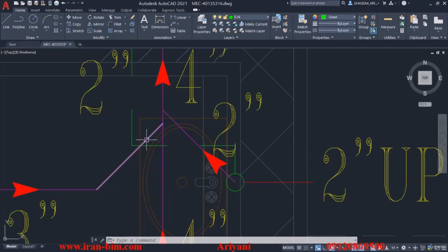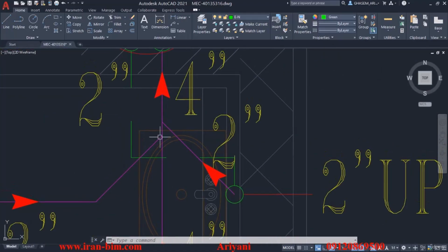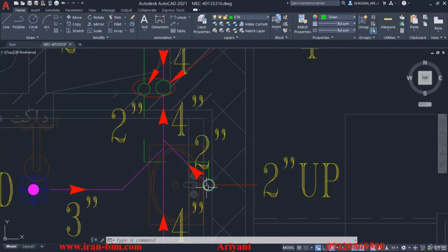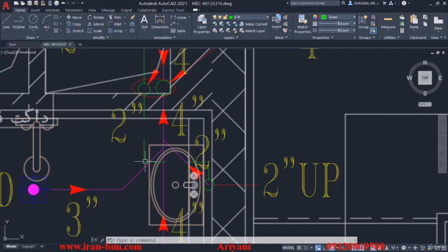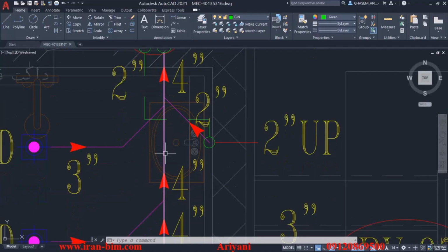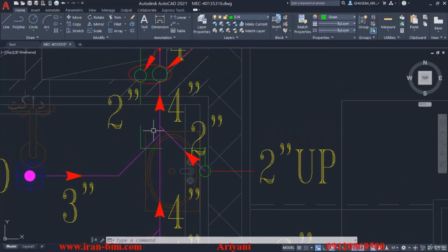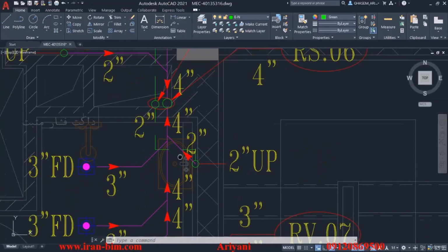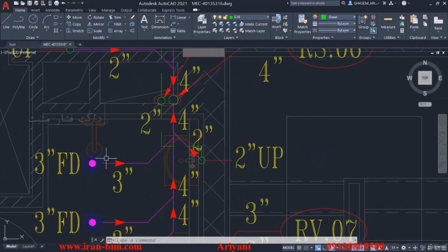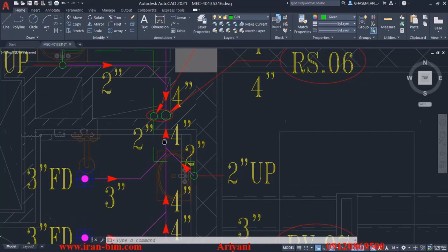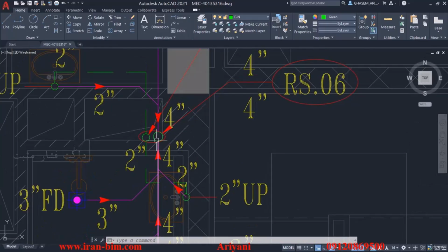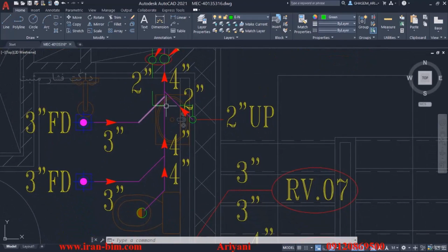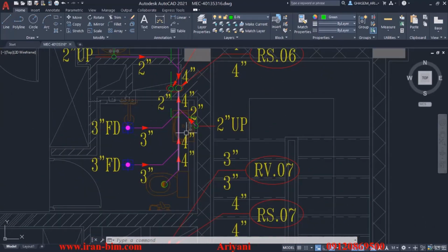But a problem that we have here is that the drain goes from a 45-degree angle pipe to a three-way fitting. Then we have a sink here on the right, which connects to the fitting through a 2-inch pipe. Then we have 3 inches at the left and 4 down. We don't have enough space to place 2 three-way fittings here. So we either need to change the direction or connect the drain to the riser from another pipe. And that's the difference between 2D and 3D plans.